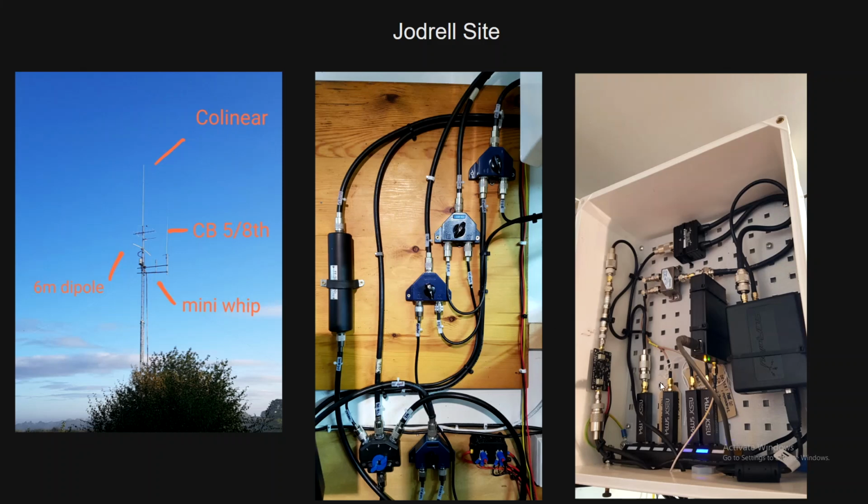In the box we've got the various dongles, and we've got the RSP1As switching. So we've got a duplexer here for 270. That's then split. The RF splitter here splits the UHF signals for 446 and for 77s. Here is an LNA basically, so an amplifier preamp. But what I've now done is this has now gone up onto the tower, so it's actually a masthead preamp. This picture was taken as I was testing it downstairs.